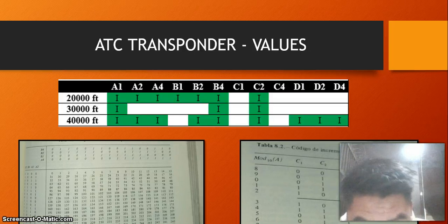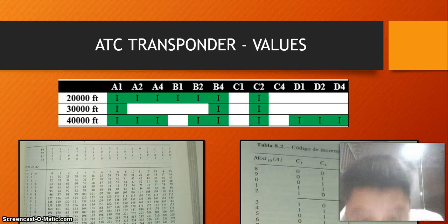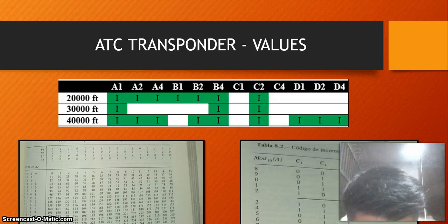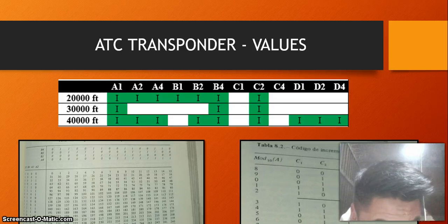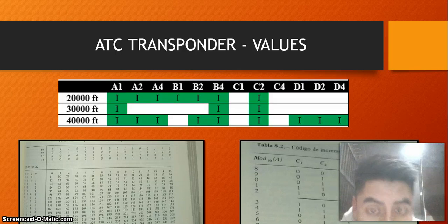It is worth mentioning that when the information is presented with irregular blinking, it means that the equipment is not capturing the information. If so, you must proceed to adjust the sensitivity of the equipment. This sets the output power to show the information without interruptions, with the respective lights indicating the values. If you still have the same problems, there are two other control knobs.